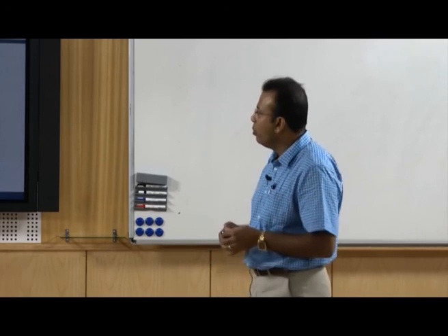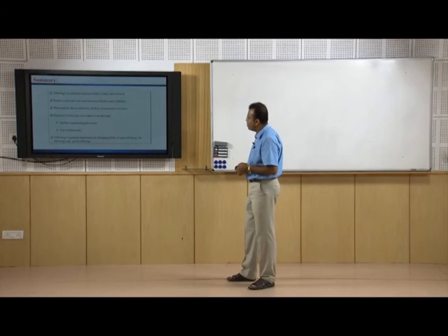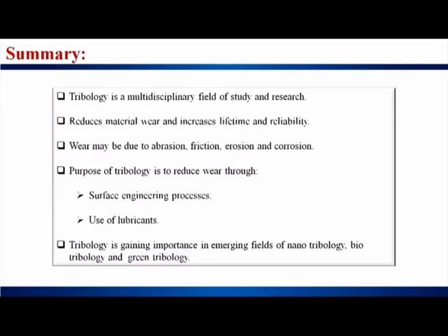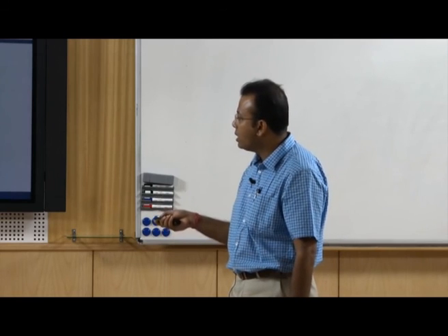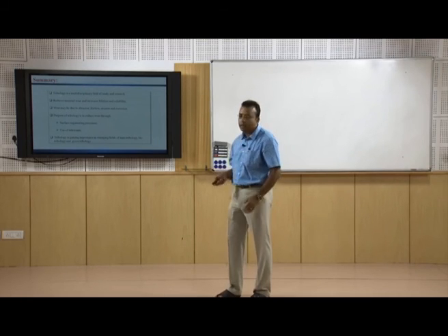As a summary, we can conclude our first lecture: tribology is a multidisciplinary field of study and research to reduce material wear and increase lifetime and reliability. Wear may be due to abrasion, friction, erosion and corrosion, which we will study in our subsequent slides. The purpose of tribology is to reduce wear through surface engineering processes, which will also come later, and the use of lubricants, so that there will be less friction and the material will retain its own properties. And the last point is that tribology is gaining importance in the emerging fields of nanotribology, biotribology and green tribology.